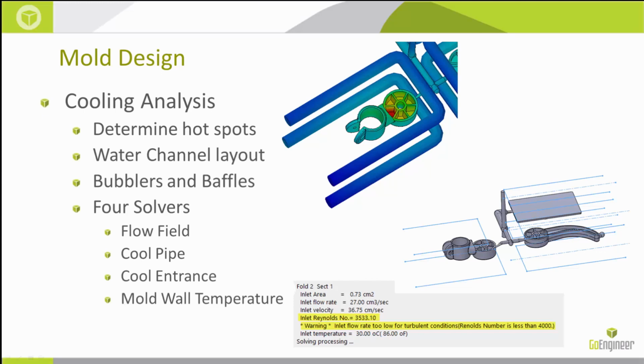The system is going to assume that all of the mold wall temperatures are uniform throughout the process. So it's almost like a perfect world scenario with mold cooling, which we know in injection molding, running your water lines through there, your flow rates, your water temperatures, materials, all of that affects the mold temperature all around your part. Your thicker wall sections will generate more heat,